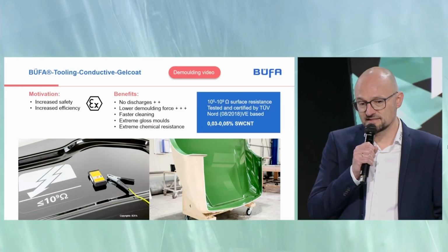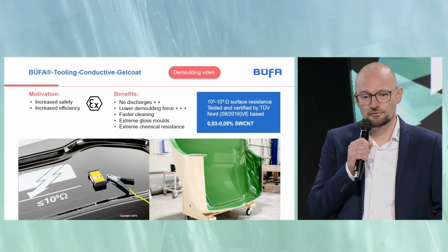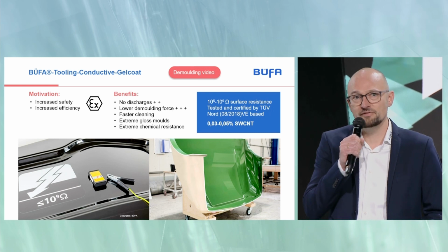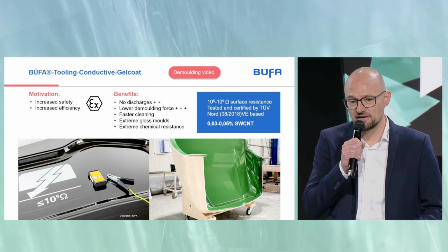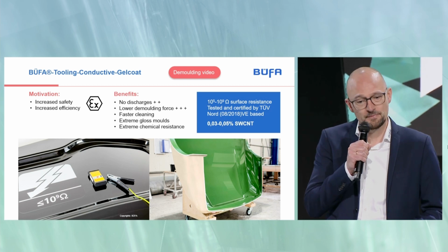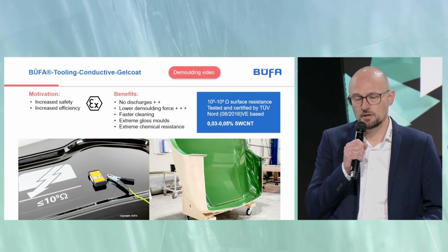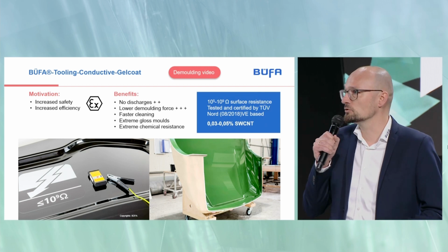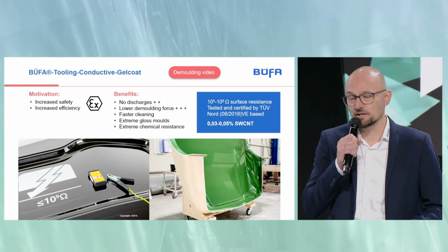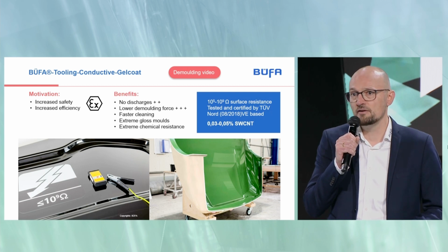We are using this technology also to create conductive tooling, gel coats. The motivation is again to increase safety, but also, and this time, efficiency. So if you have a conductive mold, you will have no discharges during demolding. This increases the safety. You will have no flashes. We also notice a much lower demolding force. So you need less force. The risk of any damages is much reduced.